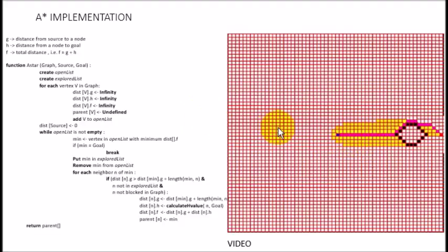The search direction, which is provided only in A star and not in Dijkstra's, is guided by the heuristics function h. It tells us how much minimum distance the current node still needs to travel to the goal. Like the heuristics function of this node would be the straight line. The heuristic function is taken to be the minimum distance in an unobstructed environment.